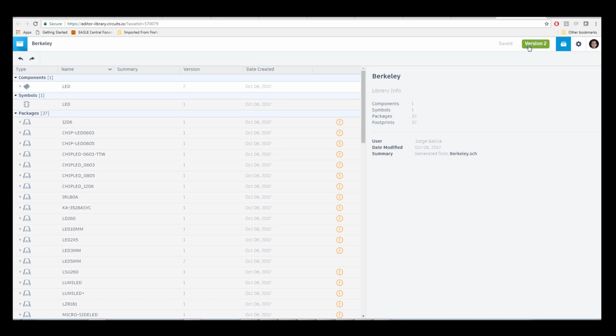Whenever you see a draft, that means you have unsaved changes. You need to make a new version. Otherwise, you can't reflect that in your local copy of the managed library. So it is vital that you always make sure that you have a version number, that you don't have anything in a draft state. Now, when you make changes to the package, those also are versioned. So it's important to keep track that you're going to have versions for your 3D packages and versions for the library itself. So it's always important to stay on top of that.